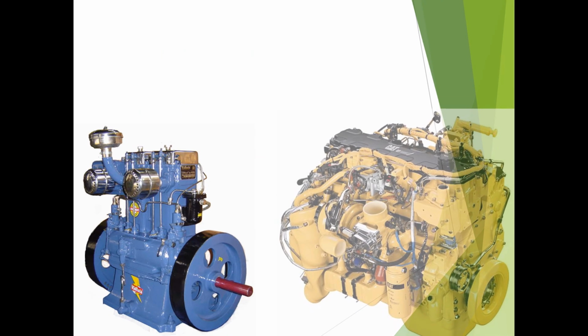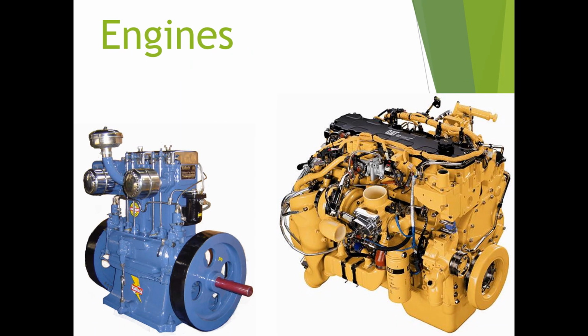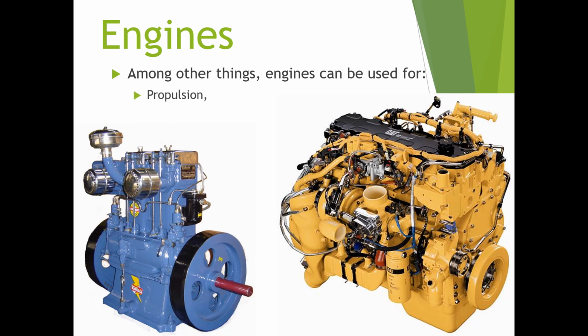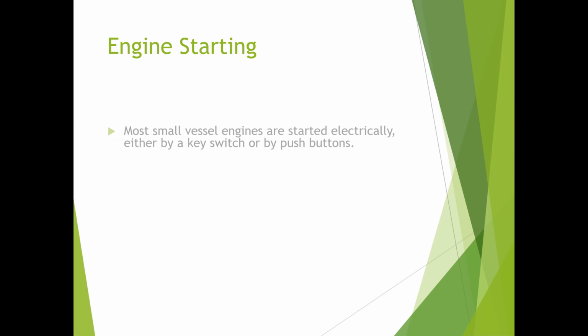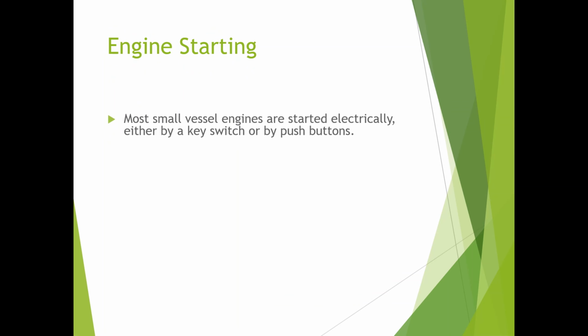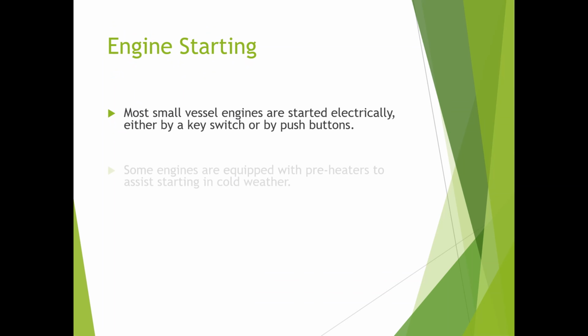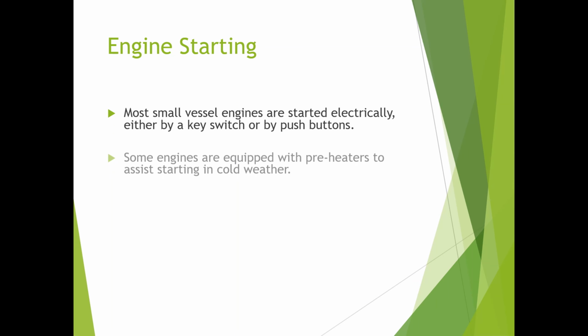Engines. Among other things, engines can be used for propulsion, for power generation and for pumping. Engine starting. Most small vessel engines are started electrically, either by a key switch or by push buttons. Some engines are equipped with preheaters to assist starting in cold weather.